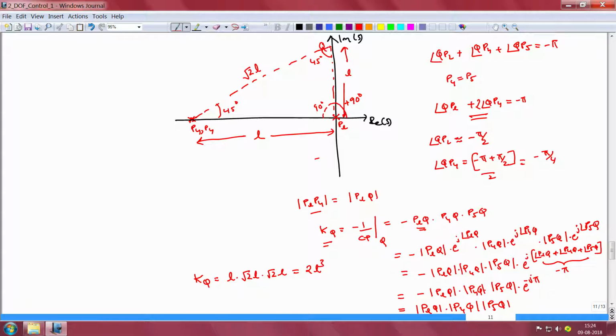Now this gain kq should be greater than the maximum gain that the open loop system would achieve on account of the uncertainty that exists in the gain of the plant itself. Now when the plant gain reaches its maximum value, the closed loop pole position PCL will be at the point PCL max, and hence the gain K max of the overall open loop system when the plant's gain is at its maximum value is given by K max